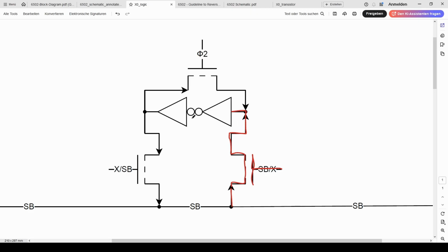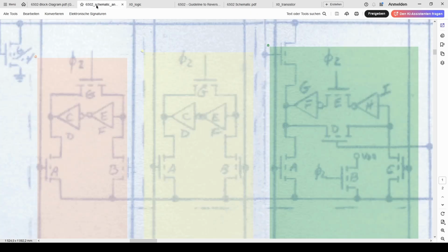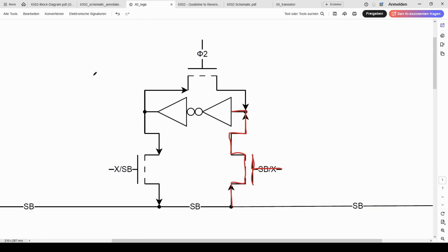This is just a double inverter. It might look weird having the circle at the input of the inverter rather than the output side, but I just copied the notation used here. You can see it a bit more clearly on the Y register here. This is just a shorthand, I guess, to make it immediately obvious which state you expect the line to be in relation to the original input. It doesn't matter much here anyways because they're directly chained.